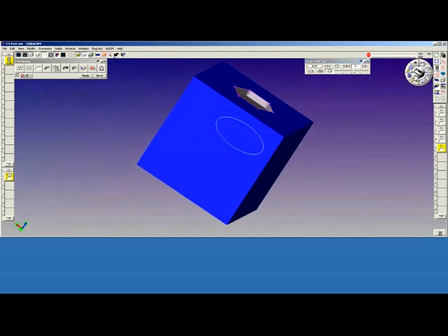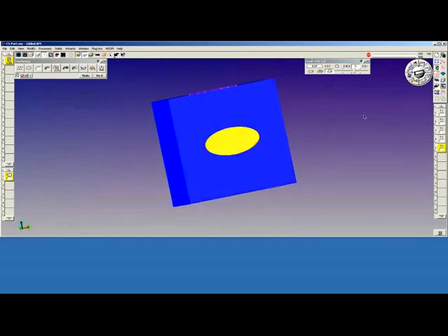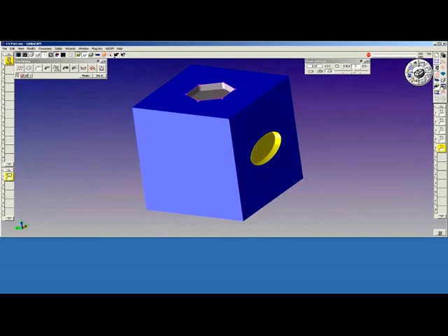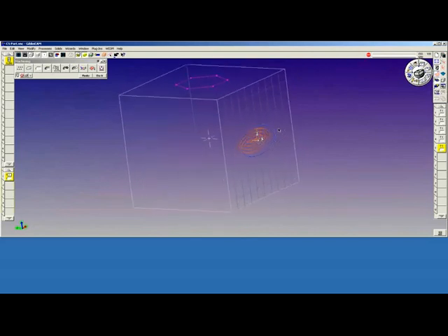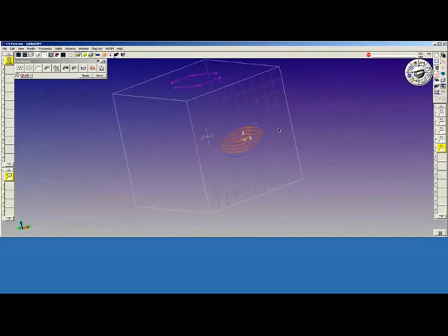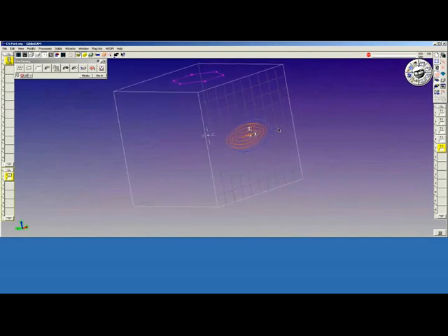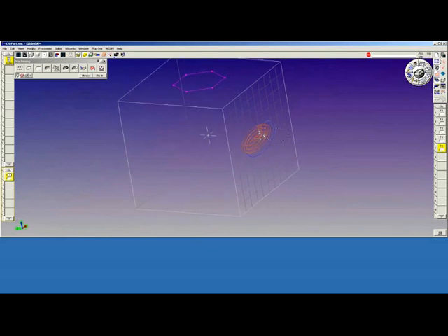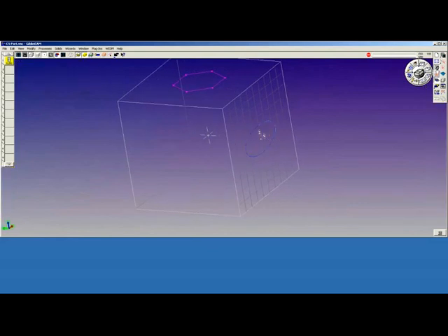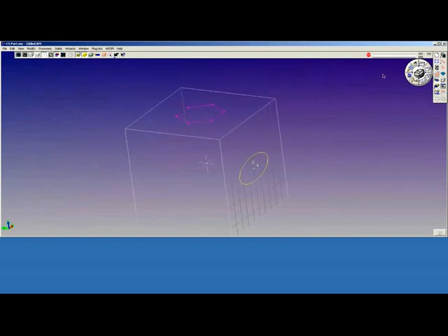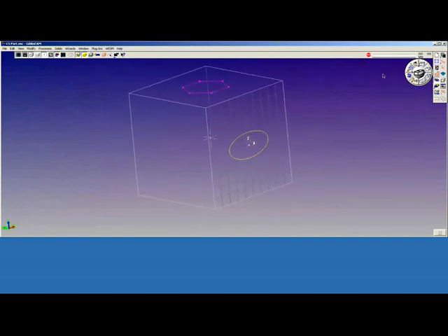All right. There we are. So now you can see how we apply machining to different CSs. Once more, let's put some machining on the bottom CS. But this time, we're going to do it slightly different. As I mentioned, work groups play a role in the geometry viewing, and they are affected by the active work group.